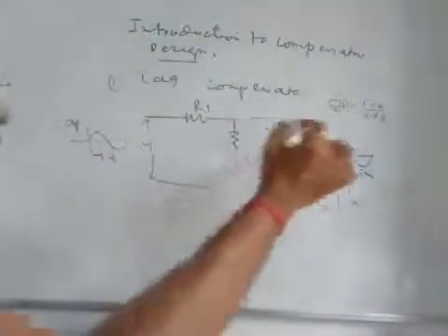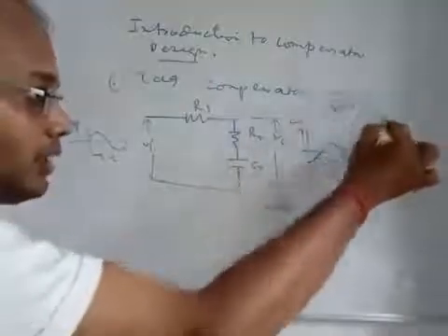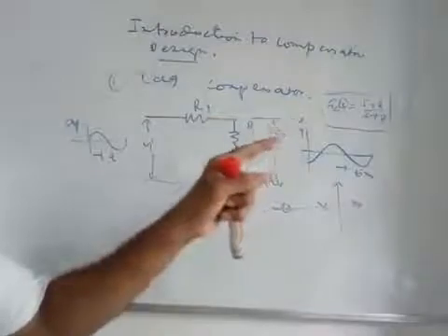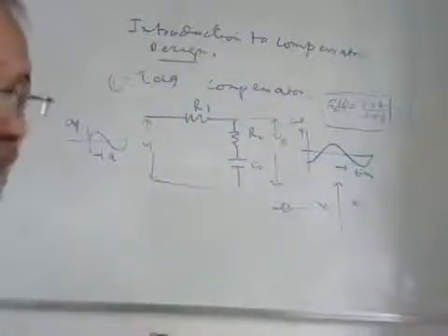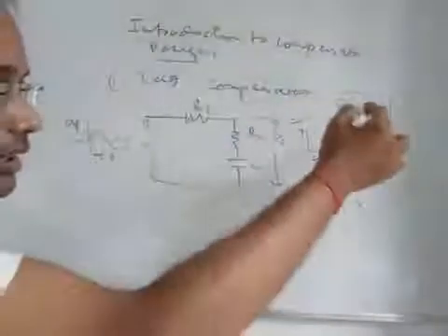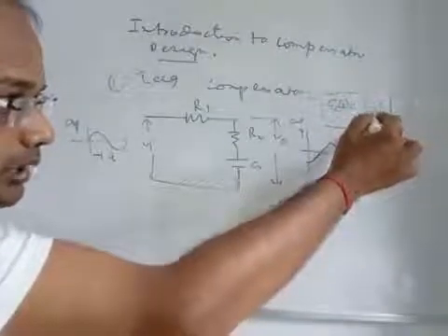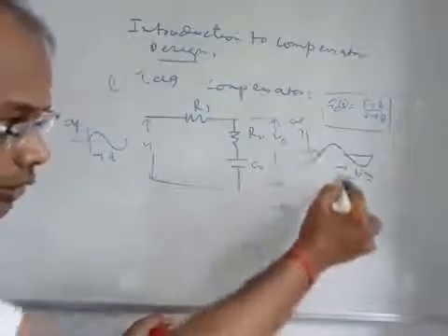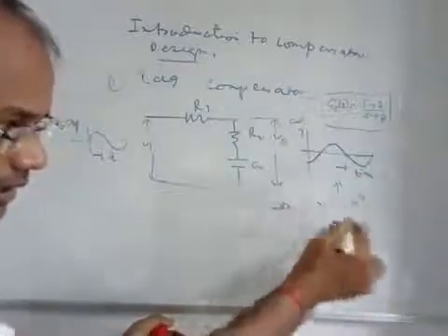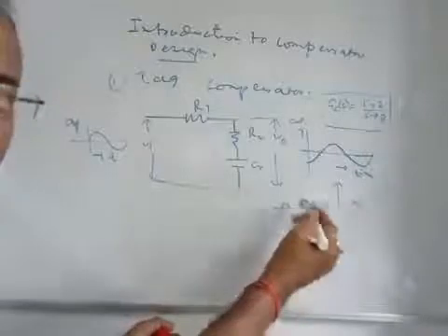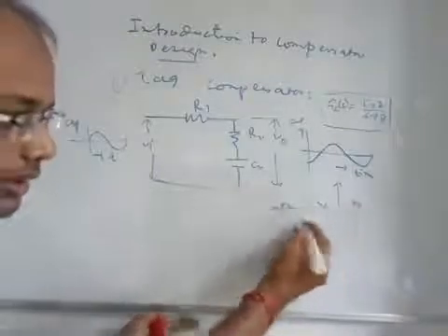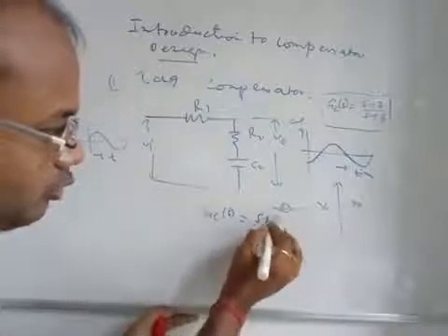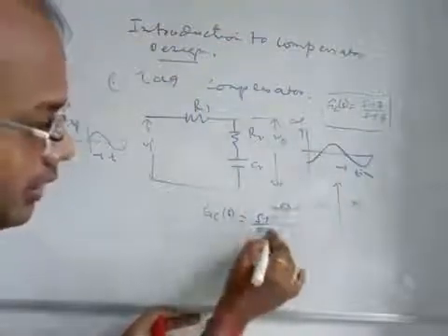Here the same type of compensator transfer function is given, with a normal structure where there is a pole and a zero. The pole is at minus p and the zero is at minus z. Here I just take the pole-zero configuration of a lag type compensator, where the structure is like (s plus 2) by (s plus 0.2).